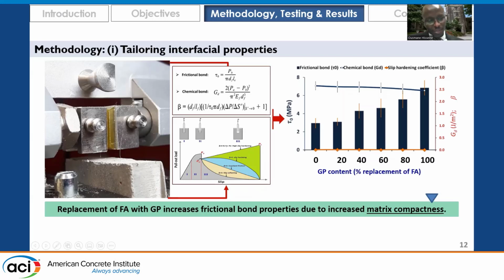This is a matrix that has PVA fibers embedded in it during the first stage, of course. The PVA fiber has an embedment length of 1 millimeter to ensure that it will be efficiently pulled out. The installation of the fiber was a very tedious, meticulous process, so that we got exactly straight, non-inclined fibers. We haven't detailed all of this here for the sake of brevity.